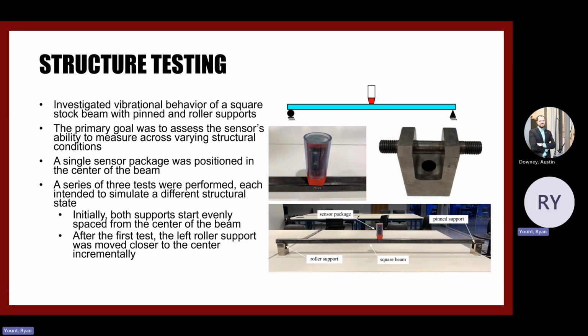Onto the actual structure testing, we wanted to create a controlled environment where we could measure the vibrational behavior of a square stock beam with pinned and roller supports. The goal of this was to assess the sensor's ability to measure across different structural conditions.